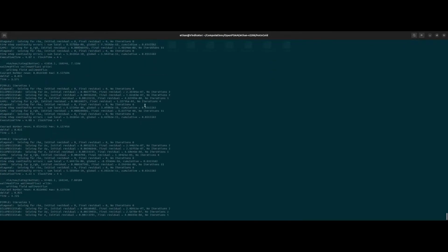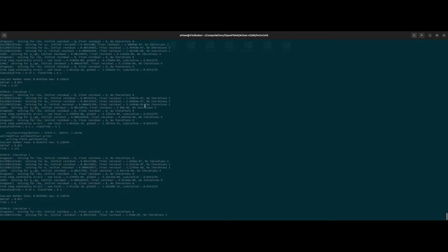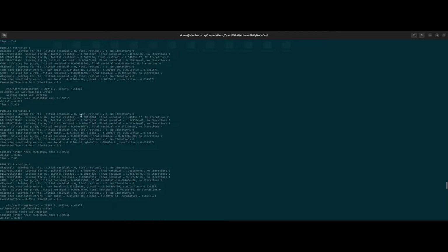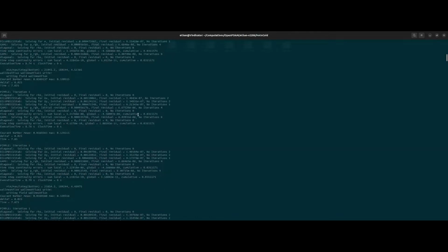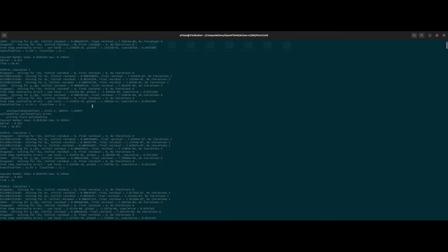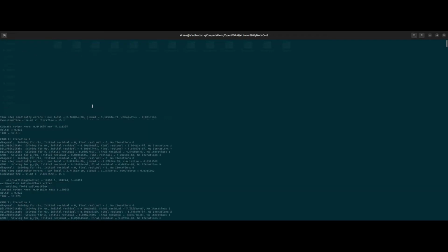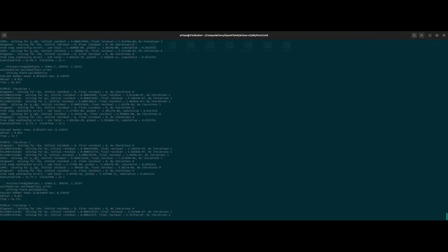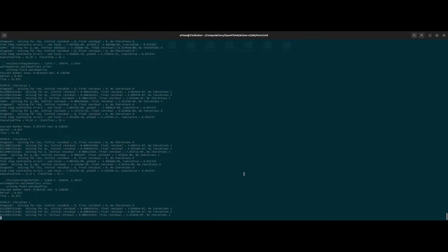So what this is doing is now it is stepping through the solver, and it's giving us residuals, and it's actually best practice to plot those, but for this very, very simple simulation, I'm just not going to. They're a little rough, but there's usually a threshold which means that they are converging. So we'll let that run.